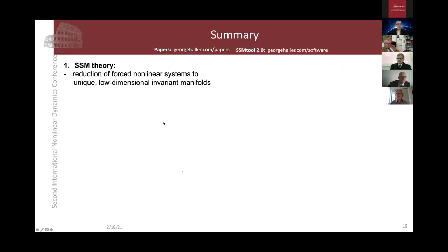A summary. I just wanted to say that SSM theory is a reduction of the forced nonlinear system, in fact, any forced nonlinear system, to a unique low-dimensional invariant manifold, okay? And with these new advances, this has stepped out of just its academic beauty and has become directly applicable to very high-dimensional systems of finite element grade. And so it can meet that challenge, right?